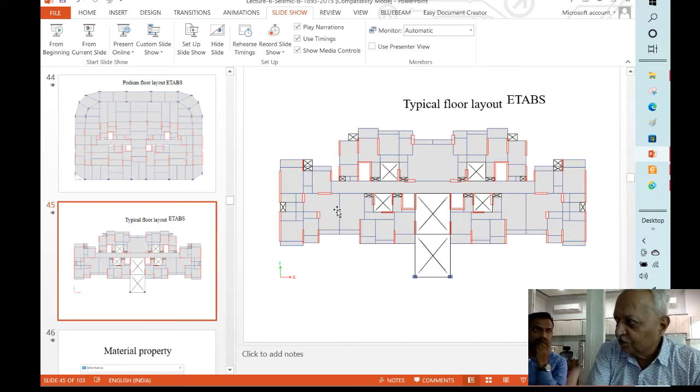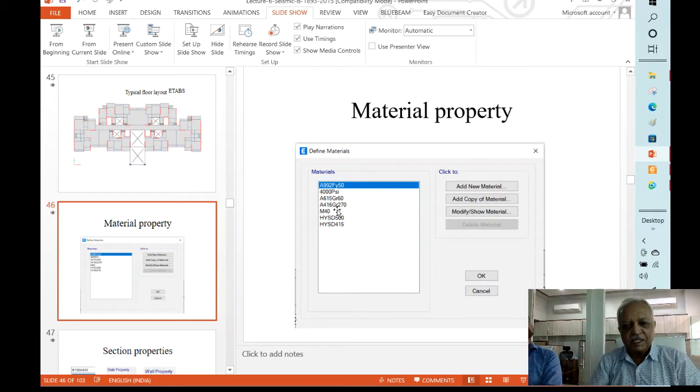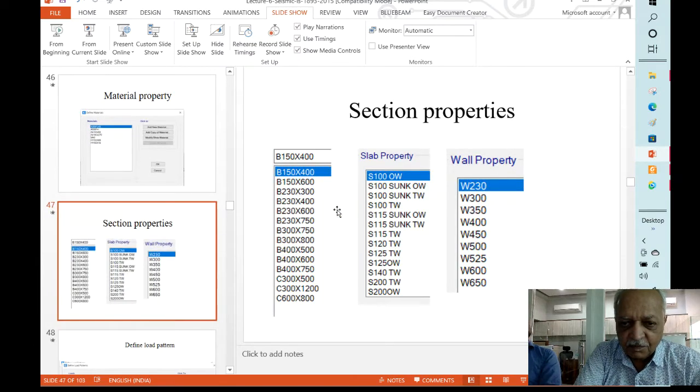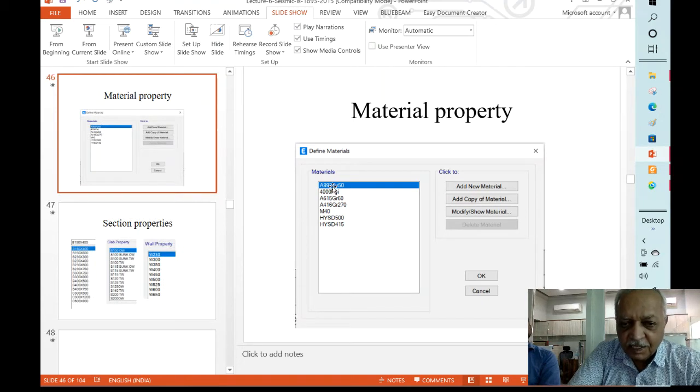After one run you design, and if the reinforcement is too large you modify the size, redo the analysis and so on. So all of that will be considered. So for material property, now we say that you have got a simple choice for deciding the material property. Using this provision, you can decide what kind of material you have got. You have got 3-4 types of materials. One is concrete, other is structural steel, if you have got concrete of different grades. Then you have got reinforcement, and if you are going for PT, then you have got the tendon also. So all of those properties are required to be defined initially.